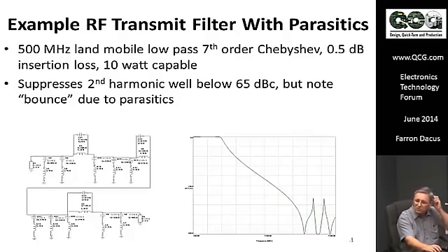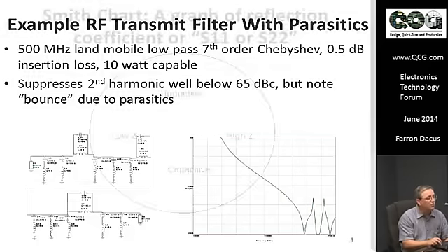Even in a very simple LC filter, you'll get this floor of attenuation of the filter. It doesn't just keep going down. So the bottom line there is you of course have to be aware of it and simulate it, and sometimes you need to use extra filter stages that you wouldn't have guessed going in because of that floor.